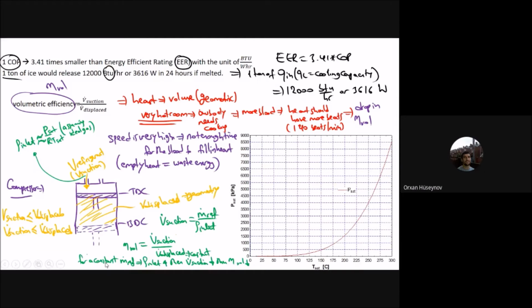That is the case for the refrigerant here. And as you can notice, if the temperature increases, the P saturation also increases, but in an exponential manner. And therefore, at the higher temperatures, you have the drop in volumetric efficiency. That is the case for the piston cylinder device here. Okay. But you have to remember that this is only for constant mass flow rate. Okay. And you can also analyze this for a given volumetric efficiency as well as for a given mass flow rate for different refrigerants.